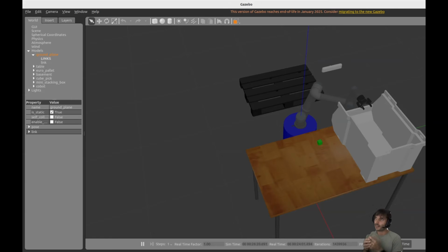If you are running an industrial application where the obstacles that we want to avoid are in a fixed position, I don't think that this Octomap feature is useful, because I'm consuming computational resources from the ROS environment in order to calculate this Octomap, and find a way to do inverse kinematics that avoids this Octomap and is constantly calculating it.